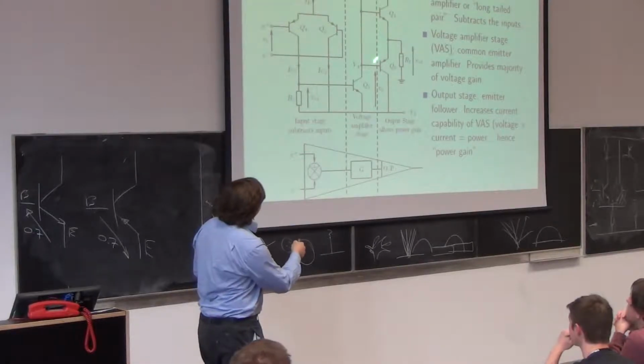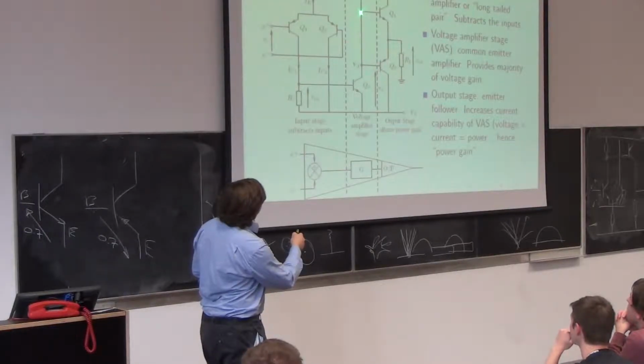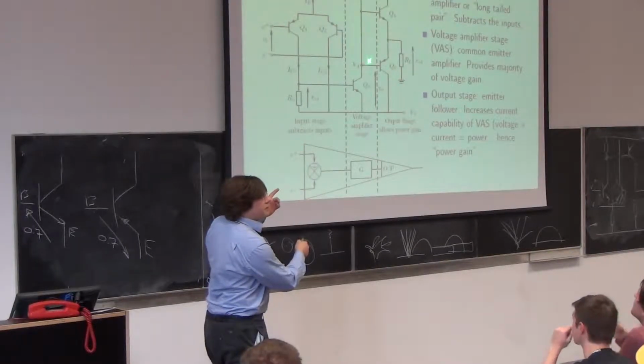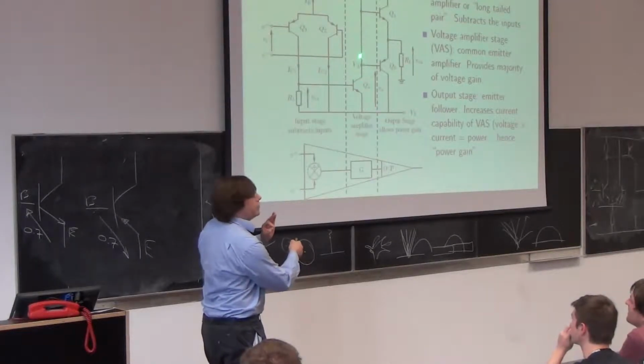And we'll assume these two are both switched on. So there's 0.7 there, with this being 0.7 above 0. And we'll assume this is 0.7 below 0. Now, the fact is I've said that's plus 0.7, that's minus 0.7. They're clearly connected together. So actually I've told you a little bit of a lie.